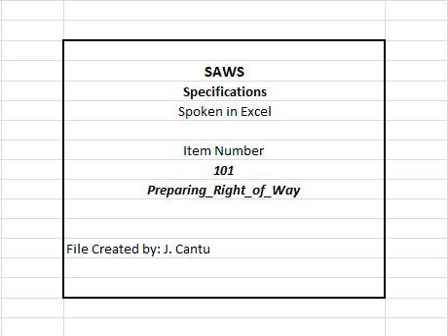8. Where a conduit is shown to be replaced, it shall be removed in its entirety, and all connections to the existing conduit or pipe shall be made. Where an existing conduit or pipe is to be cut and plugged, the line shall be cut back not less than 2 feet, and a plug of concrete not less than 2 feet long shall be poured and held in the end of the conduit or pipe. The plug may also be accomplished by using a precast stopper grouted into place.